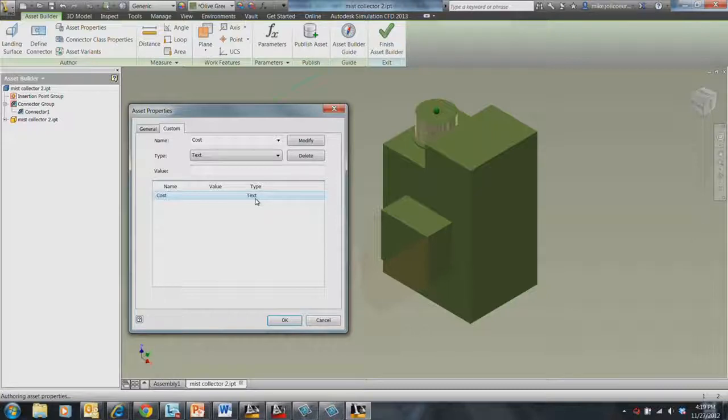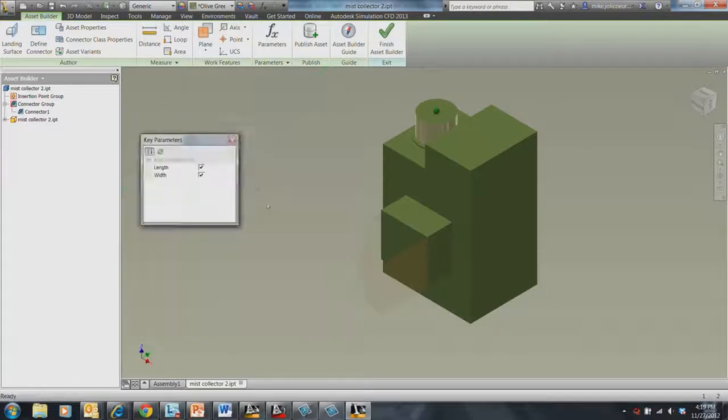Are you guys familiar with iLogic? Okay. iLogic is a language that's inside of Inventor and basically allows us to build really smart configurations. So you can tell it to turn things on, turn things off, based on whatever they are. Okay? Very powerful tool, pretty easy to use. So, yeah, the answer is yes, absolutely. So that way your bill of material information will be correct. Okay? So we've got all of that information in place.